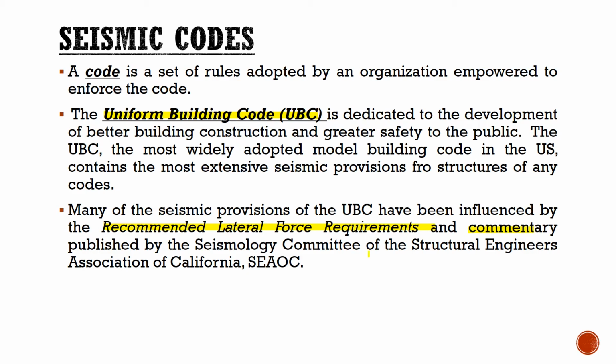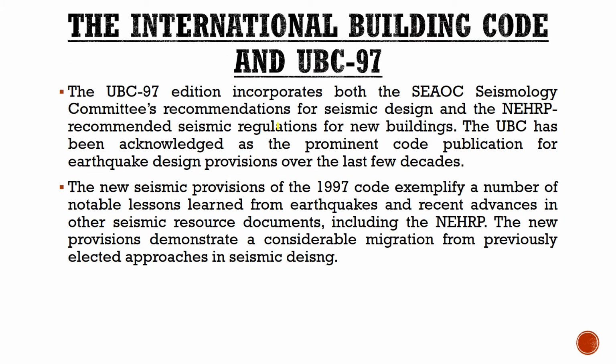Then the International Building Code and UBC 97. The UBC 97 edition incorporates both the SEAOC Seismology Committee's recommendations for seismic design and the NEHRP recommended seismic regulations for new buildings. This is the updated one as of today. UBC 97 is still what we use in our designs.